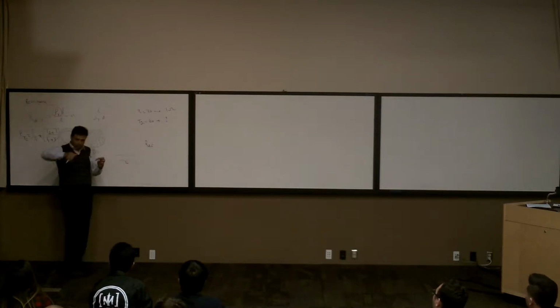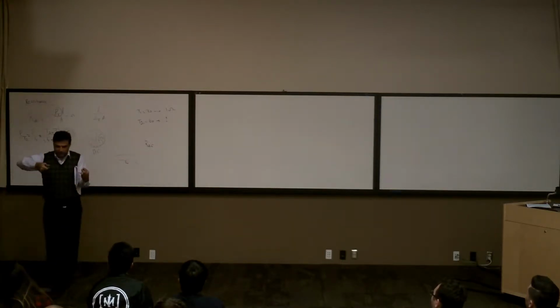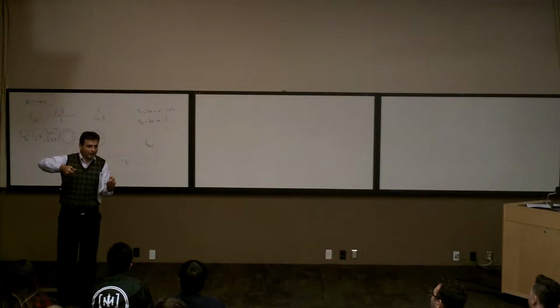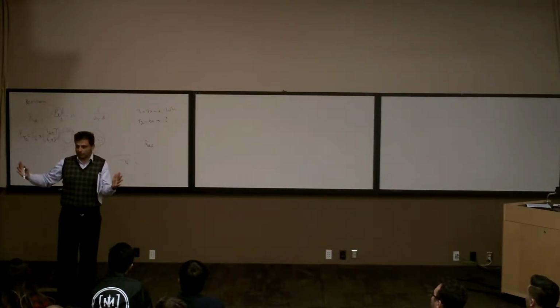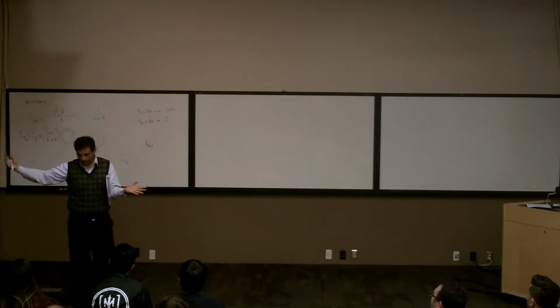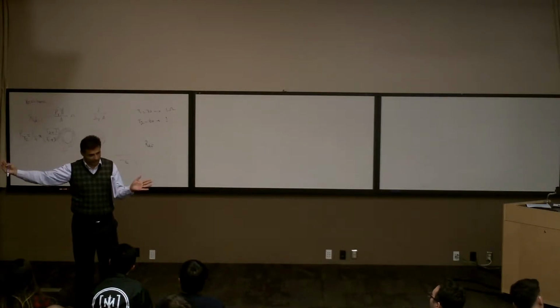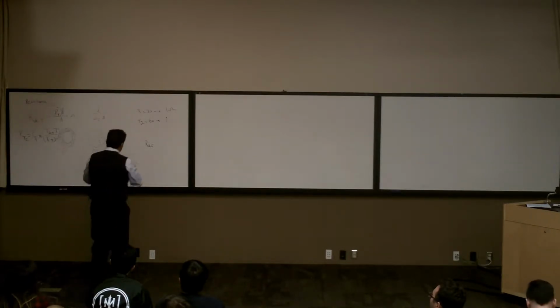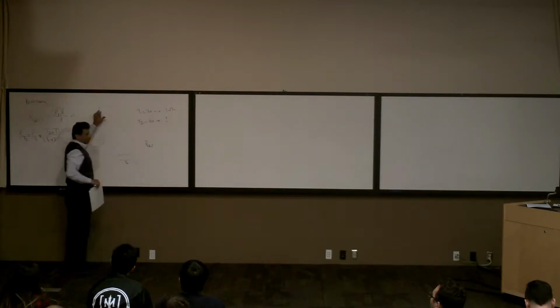You know what I'm saying? They are twisted. My point is the wires are twisted. What is the result of that? For example, you have 1 meter of twisted wire, right? If you make it straight, for example, it's going to be 1.1 meter, because the length is higher. So the twisting also is going to cause the resistance to be higher.